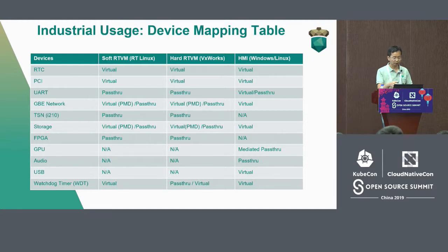And for TSN, it is a standardized protocol. Unlike the private ones, it is a public and unified standard in the industry. And its advantage is that it could help achieve connectivity between the products. And TSN is used to control the device. Like the PLC would send the network package through TSN, and then drive the motor. So the network must be real-time, and TSN is a time-sensitive network.